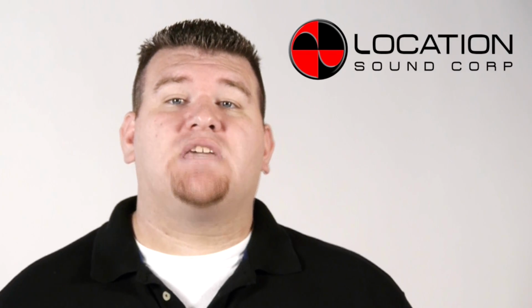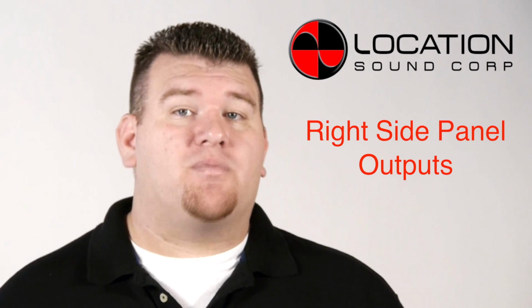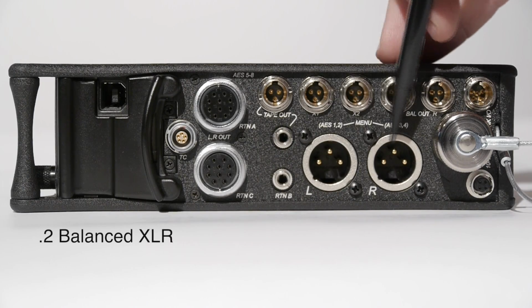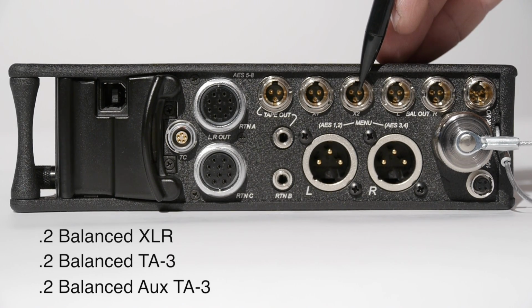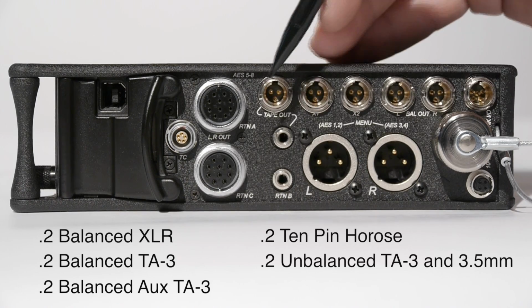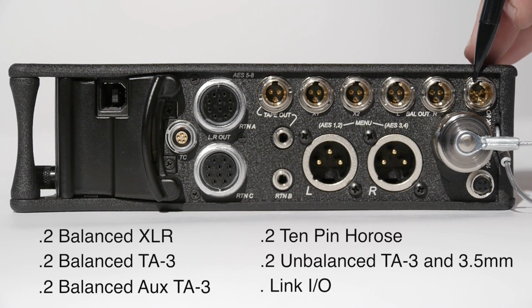In complex multicam productions, output flexibility is essential. On the right side panel of the 664 is where you'll find all of your output options. The 664 outputs consist of 2 balanced analog XLR connectors, 2 balanced analog TA3 connectors, 2 additional balanced analog TA3 aux connectors, 2 10-pin Hirose output connectors, 2 unbalanced outputs on TA3 and 3.5mm connectors, and last, a link in and out on a TA3 connector used to link additional Sound Devices mixers.